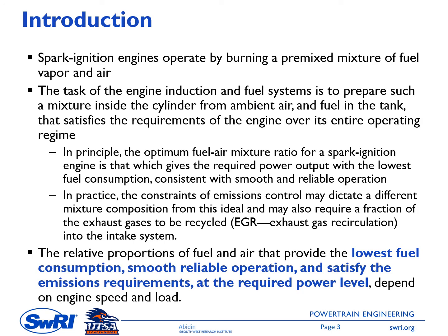The spark ignition engine operates by burning a premixed mixture of fuel vapor and air. So this is the keyword, a premixed mixture, because we have a non-premixed mixture in the compression ignition engine. The task of the engine induction system or engine intake system plus the fuel system is to prepare such a mixture inside the cylinder from the ambient air and the fuel in the tank that satisfies the requirement of the engine over its operating regime. As you know, the engine operates over a certain range of engine speed as well as over a range of engine power load.